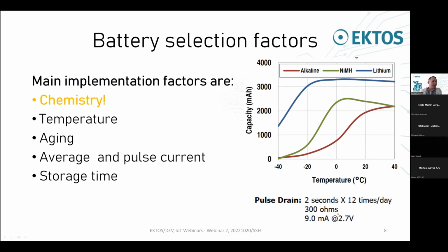This is basically from the battery datasheet. It says that the battery can do up to 9 milliamps, but it can only do it for 2 seconds, maximum 12 times per day. So this puts a limitation on your product if you use this kind of battery.